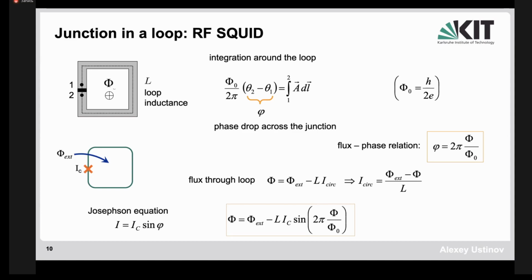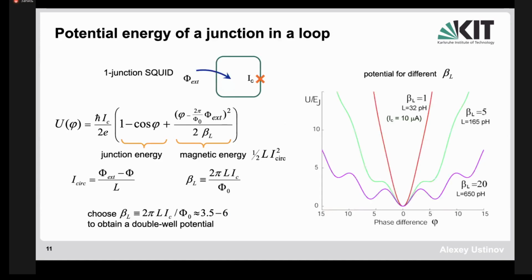And parabola goes on the sides very steeply if you go away from 0. So by choosing the value of the steepness of the parabola, which is determined by the inductance, one can actually make it possible to have a well-defined number of energy minima in this potential. To make the long story short, this flux which is entering into the energy has now the linear term determined by the external flux, and then the term associated with the Josephson junction.